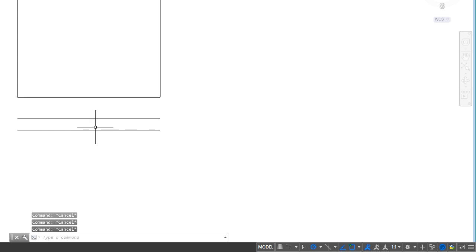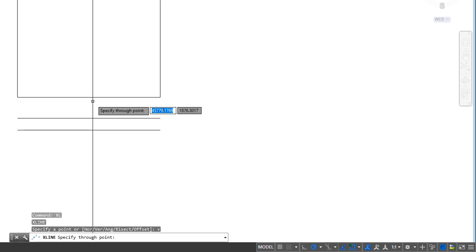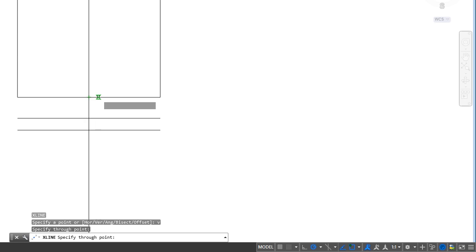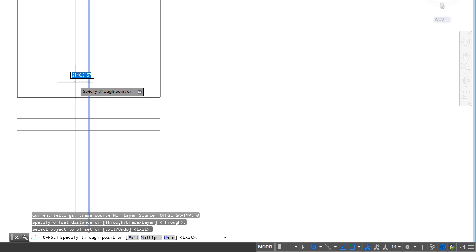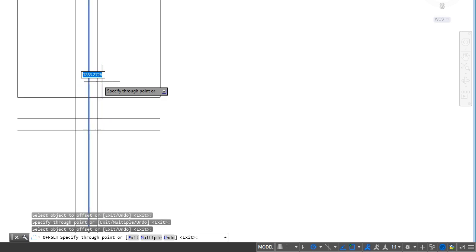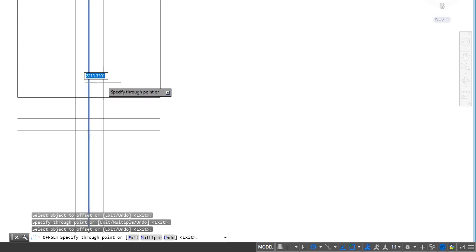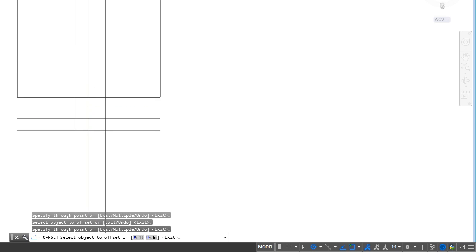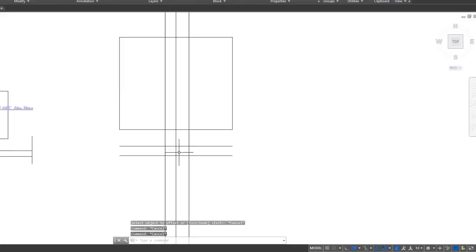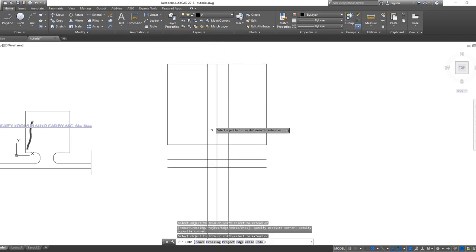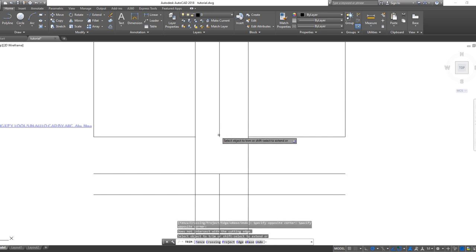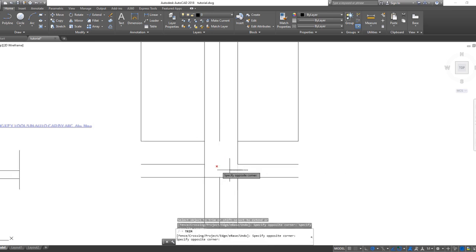Okay, so let me use my extension line EX vertical this way. Then I'll also offset the extension line this way. There are many ways you can actually achieve it, but this is just a procedure I'm following. You can achieve it in any way. You can decide to start from any part of the sketch. So now I trim, TR, enter twice, you trim here. So I trim there, I trim here, I trim here, I trim here.